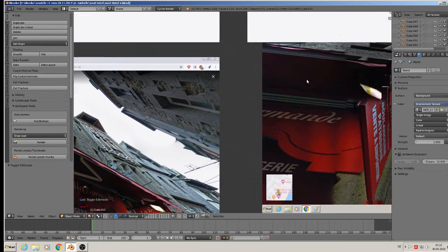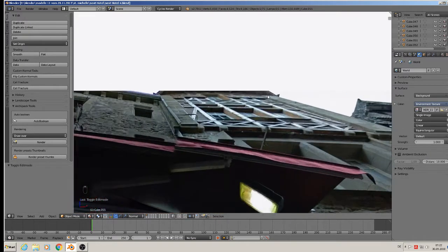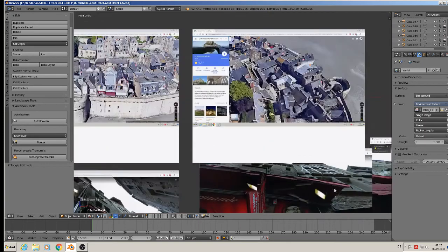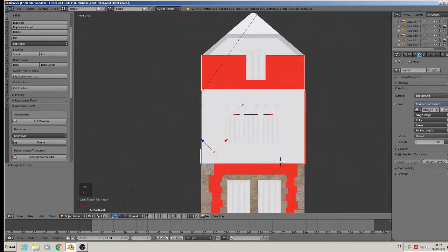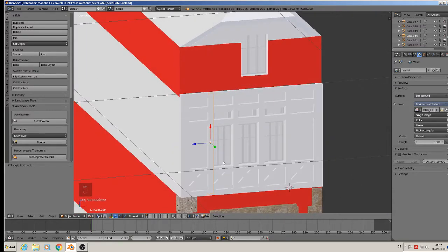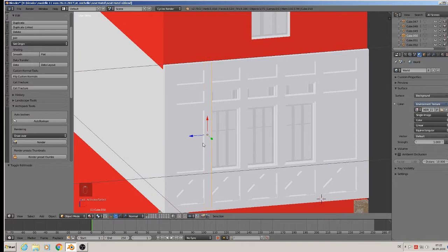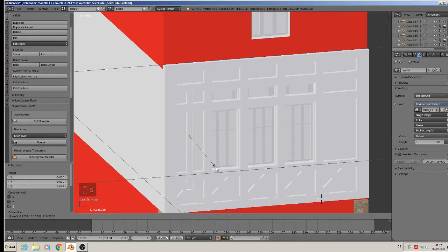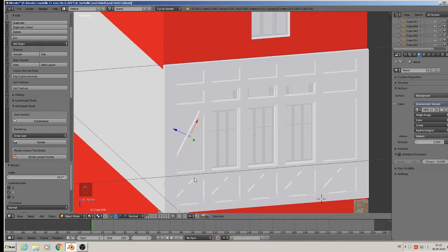Must look now to the rooftop thing there. Okay. So we'll make that. Take here this one, Shift D, and I will scale them a little and rotate Y to bring them there.